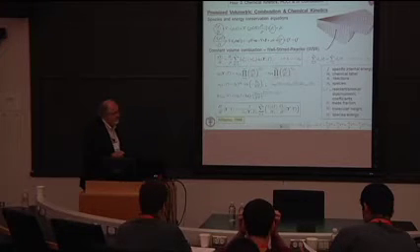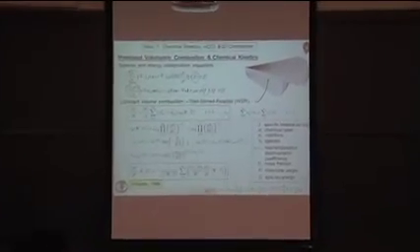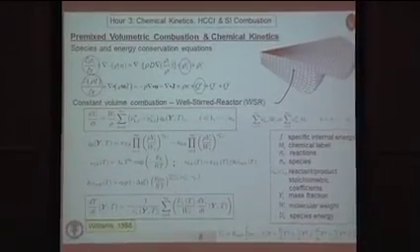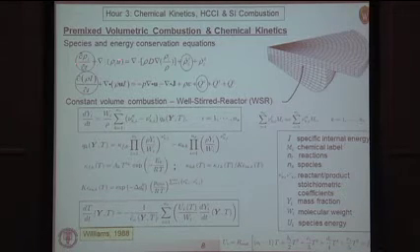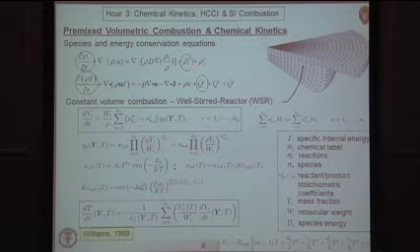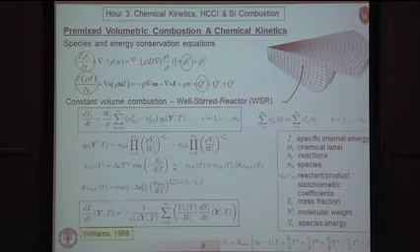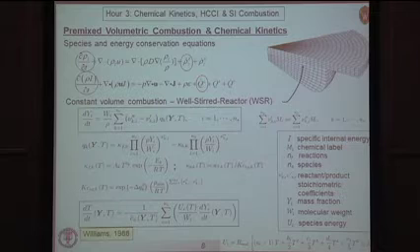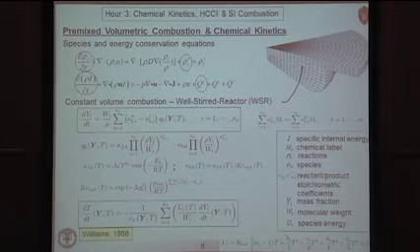Okay, so for modeling premixed charge combustion, and let's say HCCI combustion, the equations that we discussed earlier become quite a bit simpler. For example, these are our mass conservation equations for the various species. We only have to worry about the time term and the combustion source term. All of the terms involving spatial gradients we can throw out. There's no spray term, so that goes out. So in each of these computational cells in my domain here, I just have to solve these ordinary differential equations.